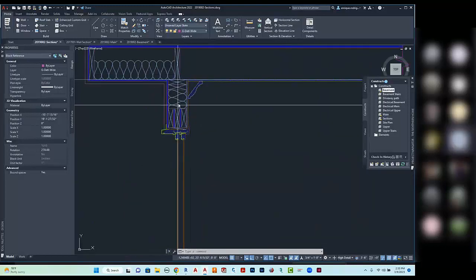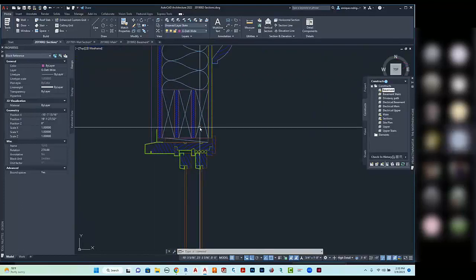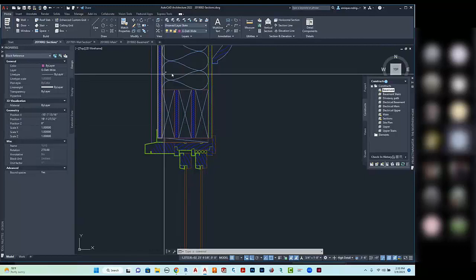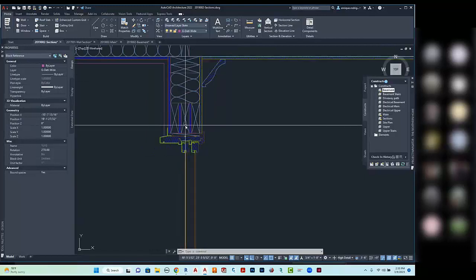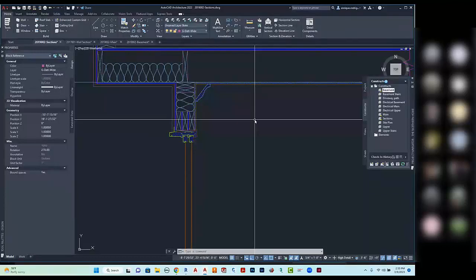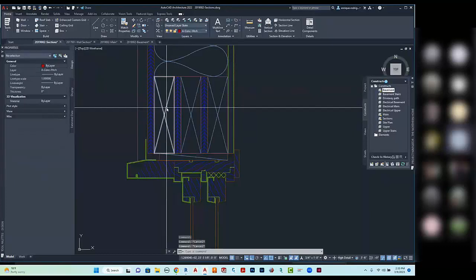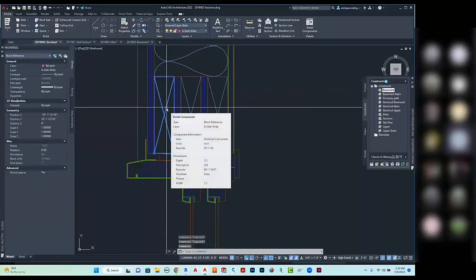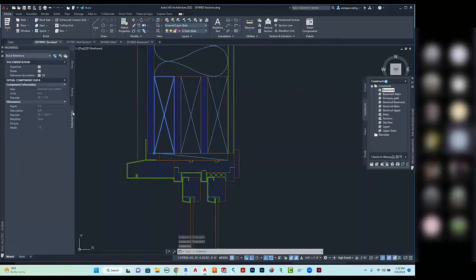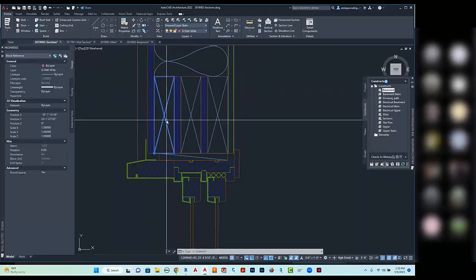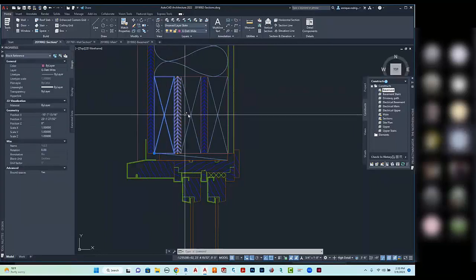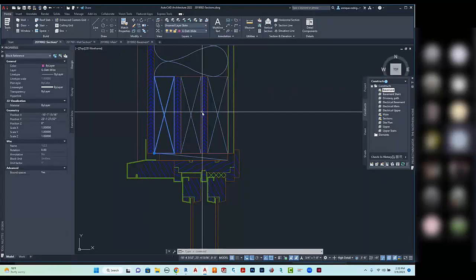The header, however, is holding up a lot of weight. So you want to make sure you have a little bit stronger element. In this case, we have a 2x6 frame wall. That wall is actually 5.5 inches wide. So what we're going to do is take 2x members in here. If you want to know what it actually is, you can see that these are 2x6s. I went to extended data, and they're turned vertically, and the space in between is filled with 1/2-inch plywood.